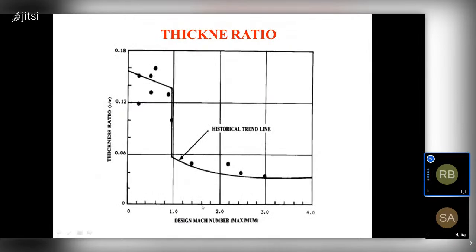If you're designing greater than Mach 1, then you have to select the aerofoil which will be in this range. For greater Mach we can select the thickness to chord ratio in that range.